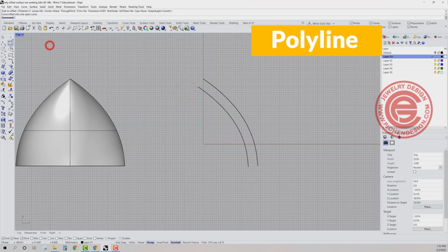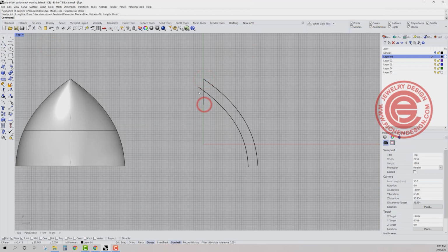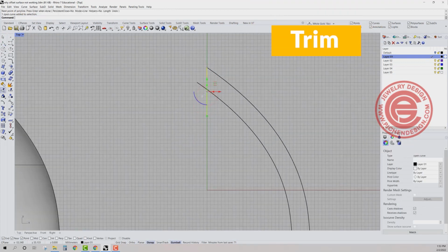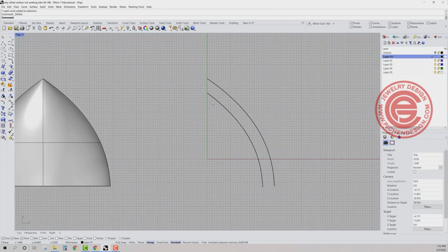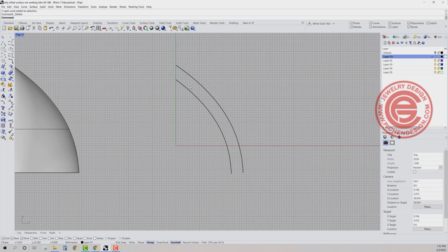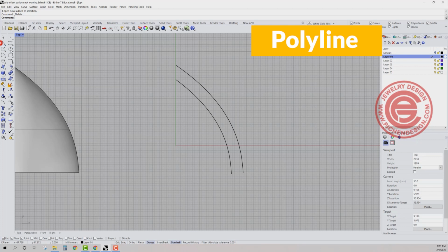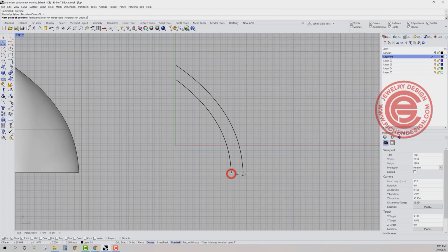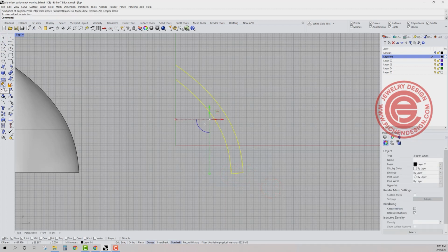Okay, then I will draw a straight line coming in this way, and use that straight line to trim all the extra that exists past the turning point that we are going to use as an axis, right? I can actually close this one on the bottom by just using a straight line. Again, you've got the polyline, and you connect the endpoint to the endpoint, and we want to use the join command to join them together.